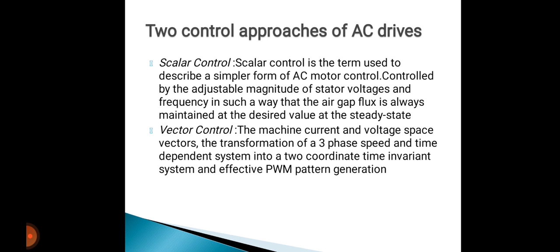If we are able to control IM and IW, the flux producing component and the torque producing component, independently, then the flux and torque can be controlled independently. In vector control, we are controlling IM and IW independently.